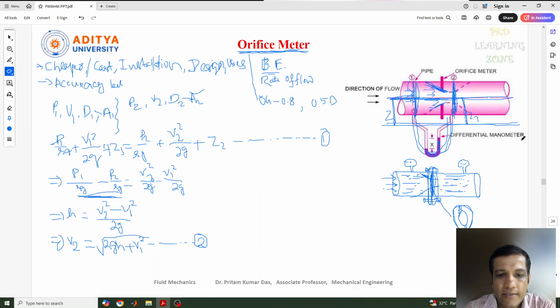So now, if you consider this is the orifice plate at this point, we can write A naught here. At this point, A naught is the area of the orifice plate. And now let me write one term, this is Cc equal to the area A2, from this orifice plate up to this second section, so that is A2 divided by A naught. So this Cc is nothing but the coefficient of contraction.